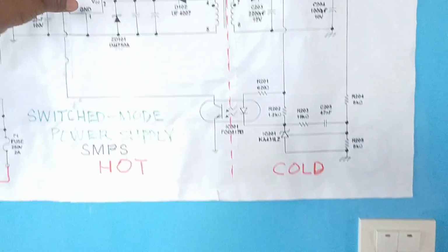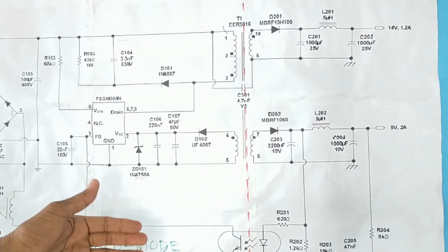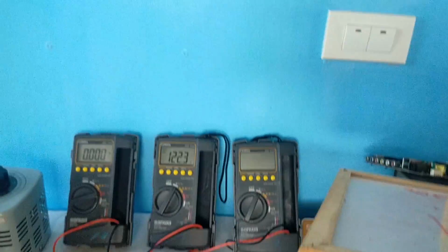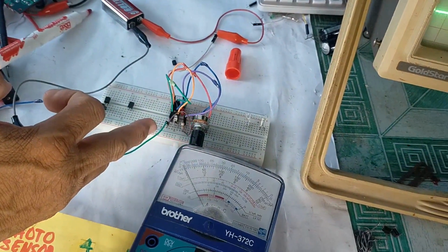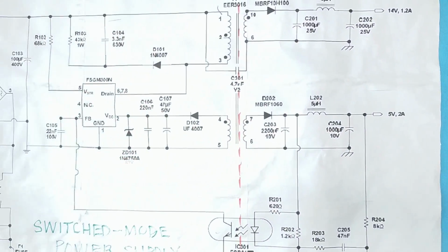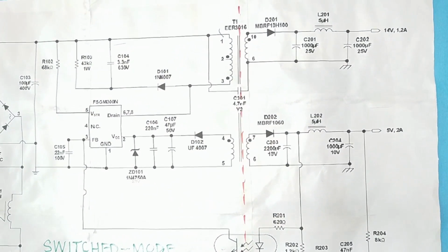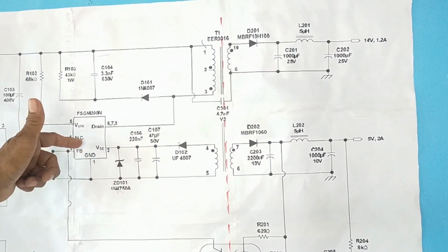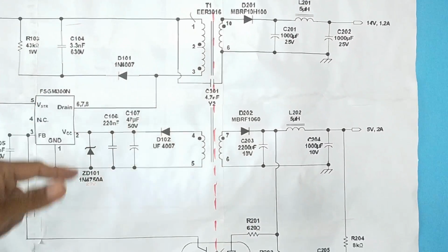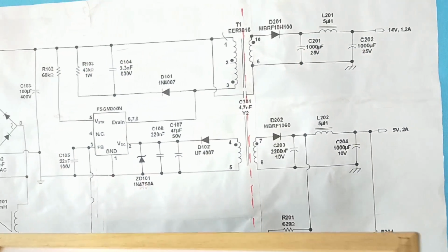Okay. So how many times the transistor turns on and off depends upon the frequency being generated by the clock pulse generator. Because the high frequency circuit here uses frequency ranging from 20 kilohertz up to 1 megahertz, let us assume that the frequency being generated by this clock pulse generator, which is located internally in this IC, is 100 kilohertz.